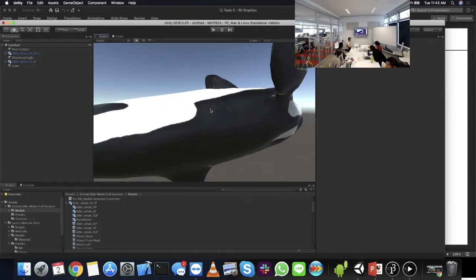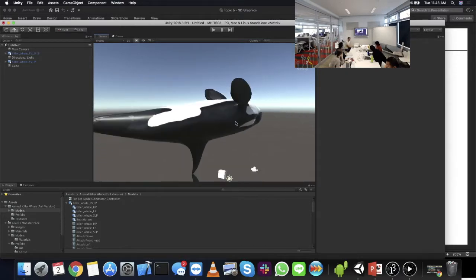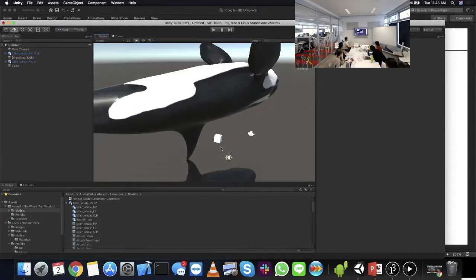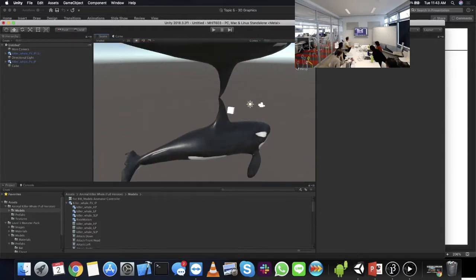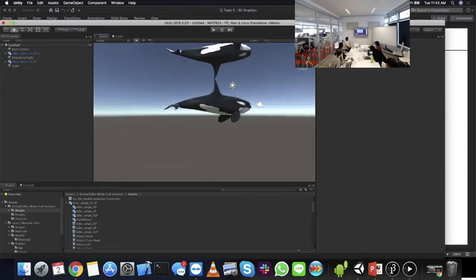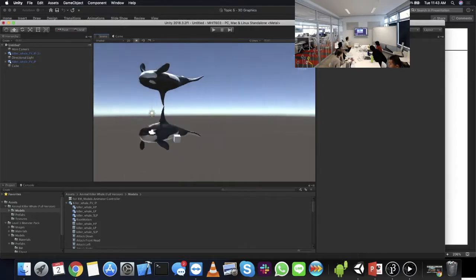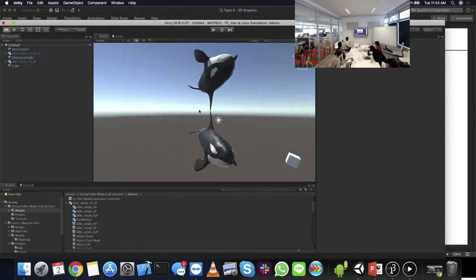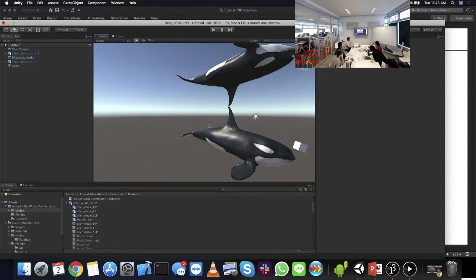So that's something I found out embarrassingly late in my usage of Unity, and it has been so incredibly helpful, just being able to click on that anytime you need to align objects together and align them in a view that gives you a measurable outcome. And then you can go back to perspective and lo and behold, everything is perfectly aligned and measured.